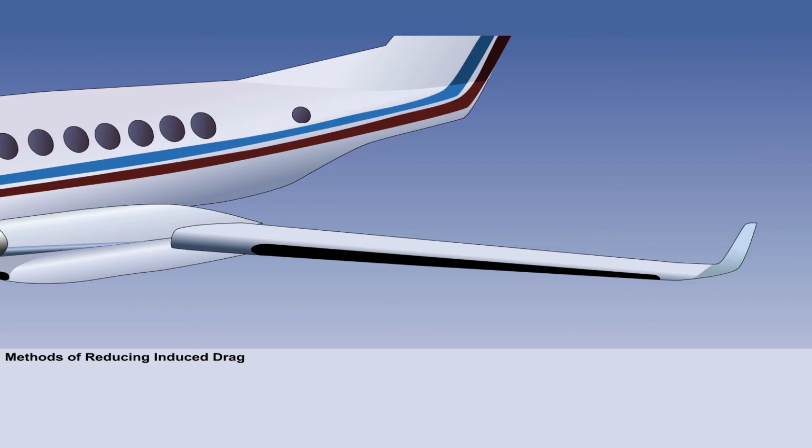From what you have seen in this lesson so far, you will know that induced drag is low at high speeds, but at low speeds, it comprises over half the total drag. It has also been shown that a high aspect ratio wing reduces the strength of the wingtip vortices for a given lift force, but that there are practical restrictions, both structural and aerodynamic, on very high aspect ratio wings. So other methods of reducing vortex strength have been devised.